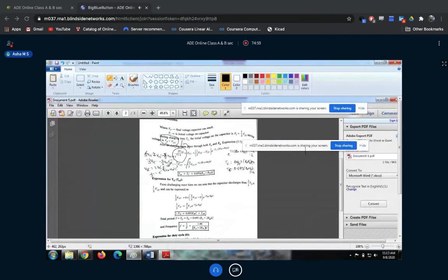If you cancel VCC and the denominator and rearrange the terms, 1/2 is equal to e to the power of minus T over (RA plus RB)C. If you take the reciprocal, e to the power of x is equal to 2, so T on is log 2 base e into (RA plus RB) into C.